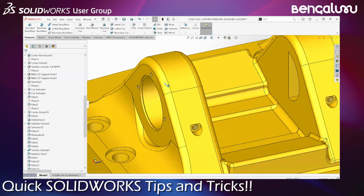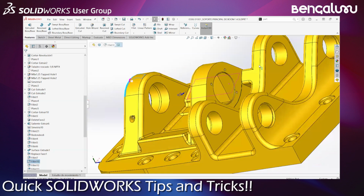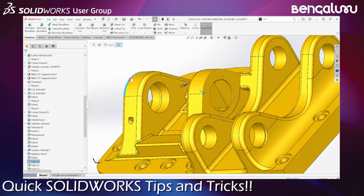And the second thing is, most SolidWorks commands work like any other application. For example, if I want to copy this fillet, I can do a Control C, select this particular edge and do a Control V. It copies the fillet with the same value onto this edge. It's not just with fillet. Any other command, it may be a chamfer or whatever, Control C, Control V, or Control X and Control V works. It's like any other Windows application, and it's as easy as that.